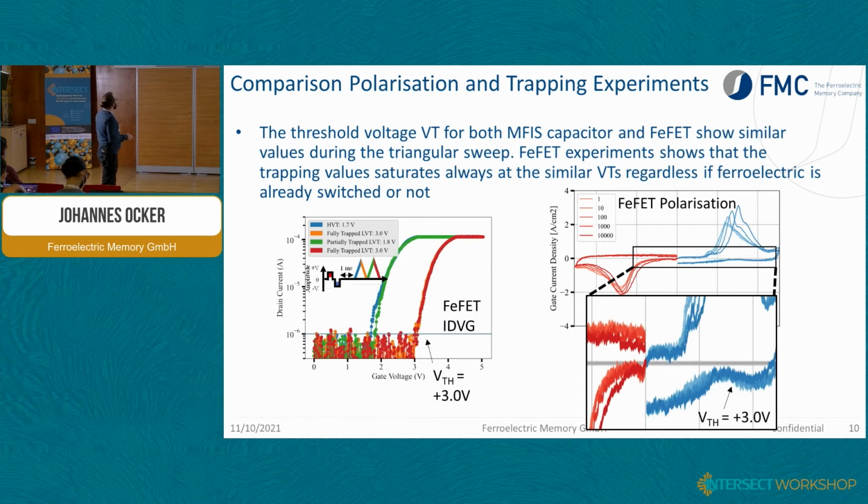Okay, so the first thing is that this is a polarization measurement, so you measure the displacement current of the transistor, and you can also see the depletion capacitance of the transistor here in this example. But we really wanted to make sure that this depletion capacitor and that this experiment really corresponds to what we can see in an actual ferroelectric transistor over here.